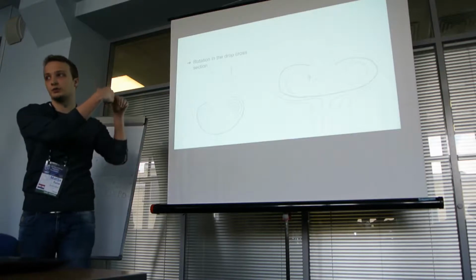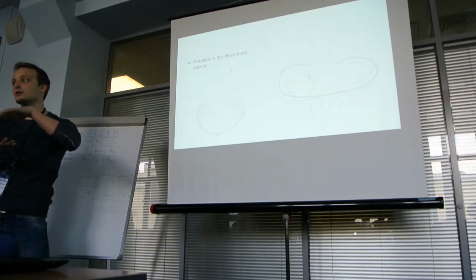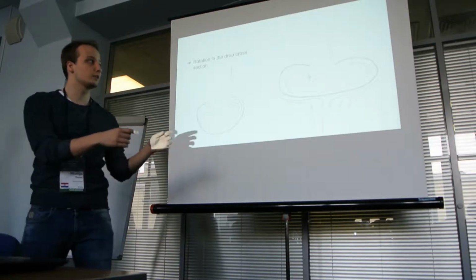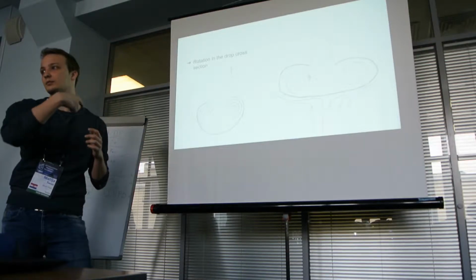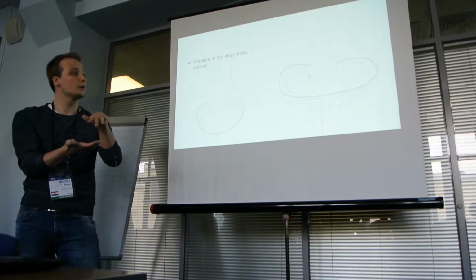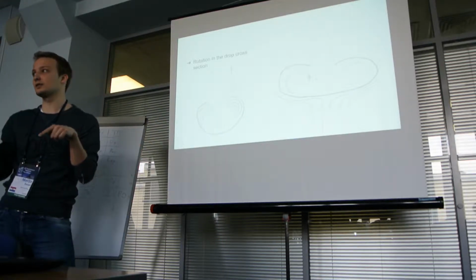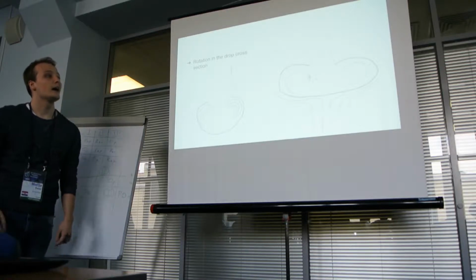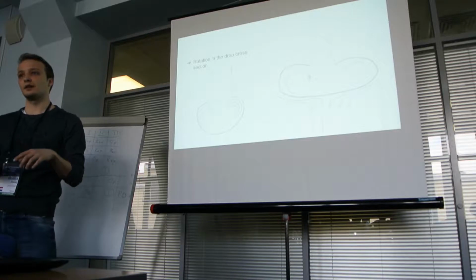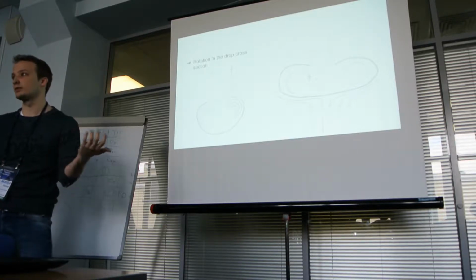We have two vortex motions, but as the drop falls, it flattens because of the drag force, and we would expect that this vortex motion is elliptical because of the shape of the flattened drop, but actually it is circular because it's a more stable motion than elliptical. And this circular motion, like in this picture, causes the flattened drop to deform to a ring, or a torus, to be more precise.